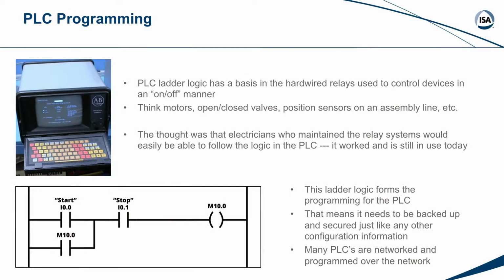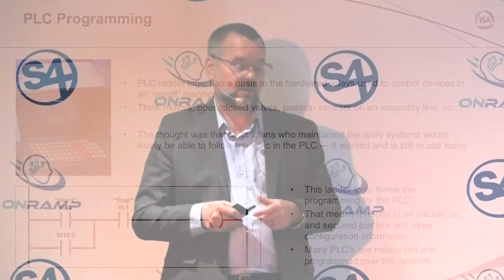So they basically took the nomenclature, the diagrams that the electrical community used, and made that the programming language. It looks a little foreign to most computer programmers coming out of university today. They go, ooh, that's different. Many of the PLCs now, you can interact with them in different ways, so they have object-oriented or layered structured programming tools to view the logic in different ways. But you'll see on the factory floor, a lot of the ladder logic still gets used.